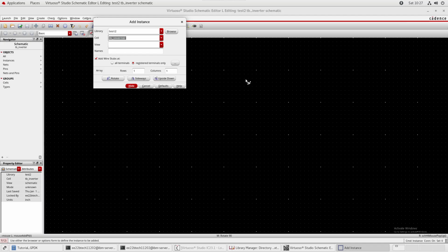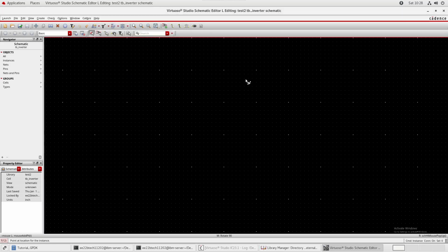It will say there's a circular linking, so it won't allow you to do it. Inverter base, that's a symbol available for it, and the same things you can do here as well. You can put multiple of them in an array, column, rotate it, mirror it, all this, like the symbol itself,